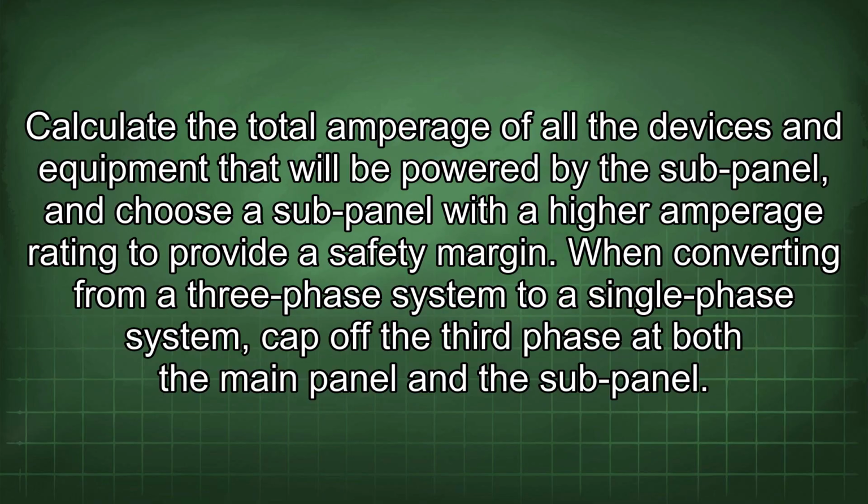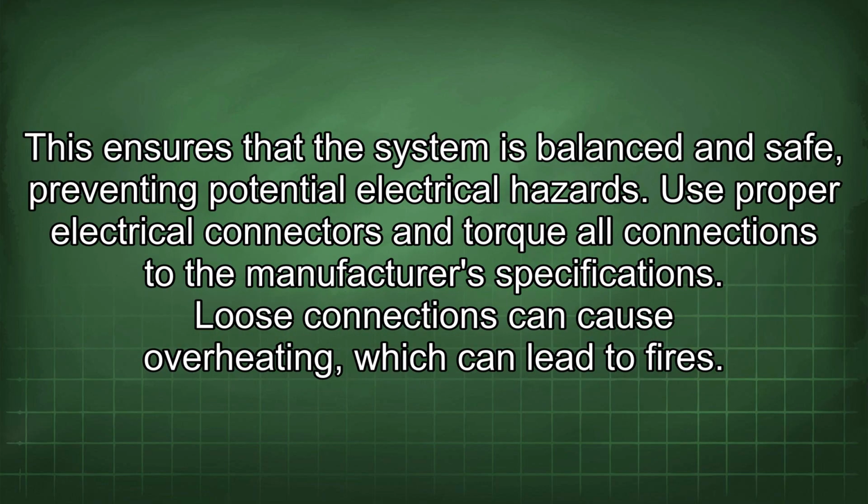When converting from a three-phase system to a single-phase system, cap off the third phase at both the main panel and the sub-panel. This ensures that the system is balanced and safe, preventing potential electrical hazards.